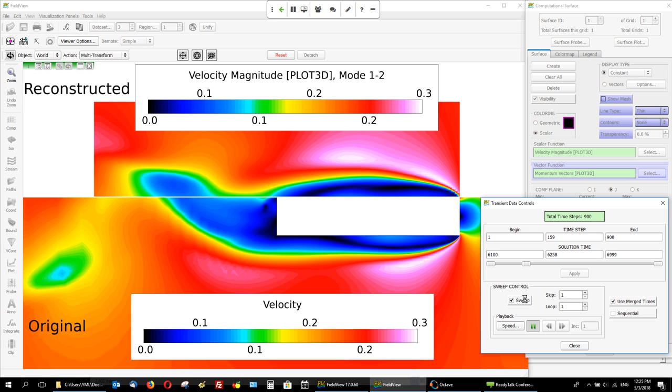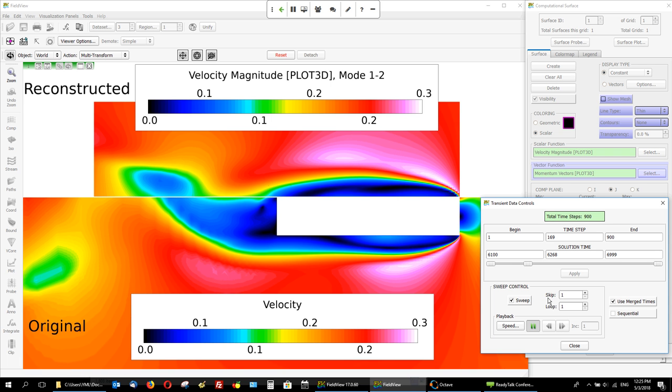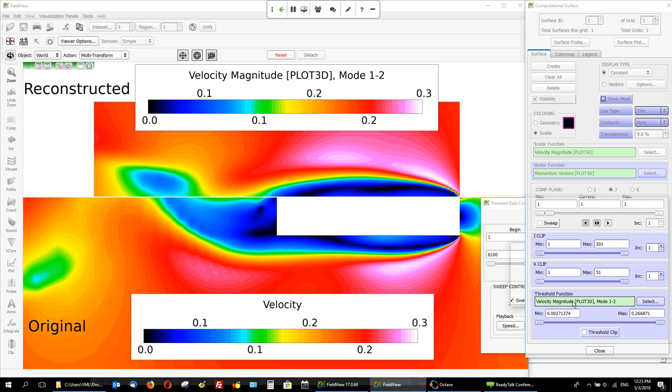And as we get to that point, that reconstructed field with just the two modes is really showing us kind of too big a vortex. So what is good is that the vortex really has been captured with these two modes, but it's a bit too wide, and especially we're missing some information of what is happening between this vortex and the rest of the flow.